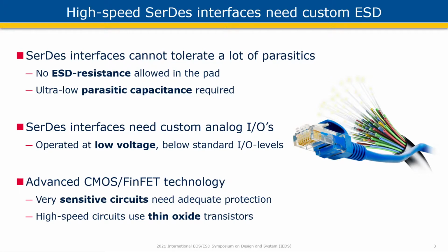Second, SerDes interfaces are frequently operated at low voltage, below standard I/O levels. Third, high-speed SerDes are built on the most advanced process technology nodes, using thin oxide transistors. These thin oxide transistors are easily damaged under ESD stress, as seen in the next slide.